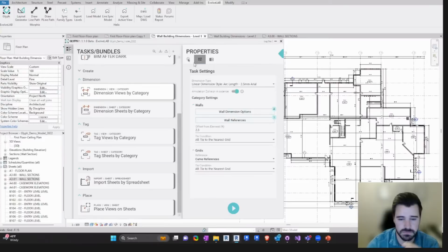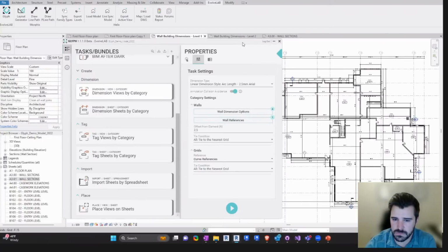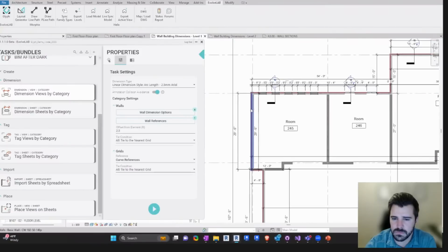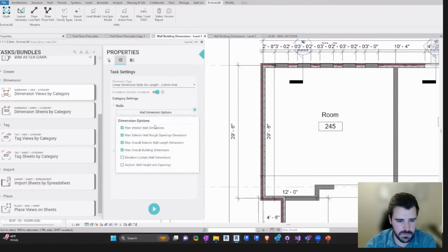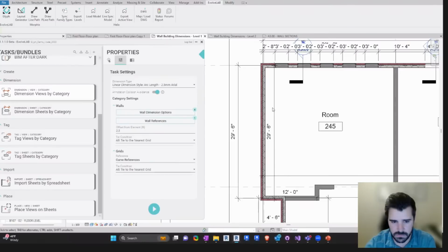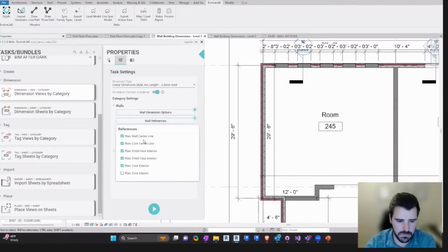That's awesome. I think before we jump into tags, because I think that is a good next step, there was a question about dimensioning one structure layer to another structure layer. So in those wall settings, maybe if you had brick or a facade in the same wall type, can you go from finish layer 1 to finish layer 2 or a structure layer, instead of just choosing one? I don't remember what the wall options were for the dimension options, but if you wanted to dimension a couple layers of that wall instead of just one layer, you just select whatever you want. If I understood correctly, yeah, you can just select multiple. And it all depends on the function of that layer, whatever that setting is in the wall type, so it depends on what's in your project. Got it. Exactly. Cool.